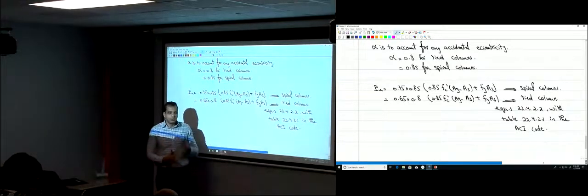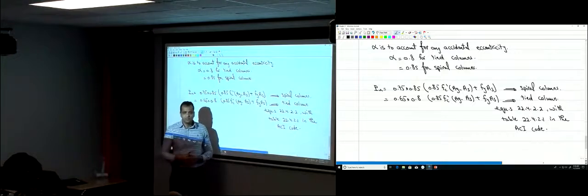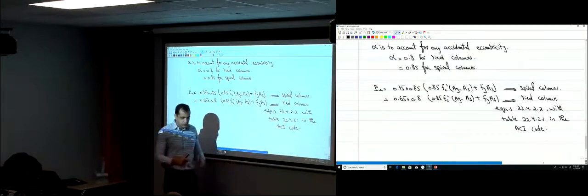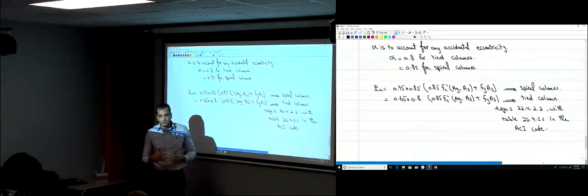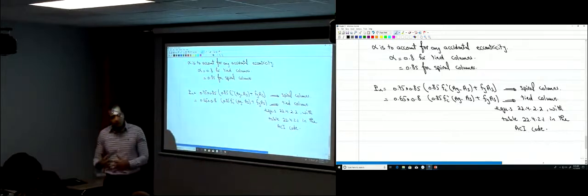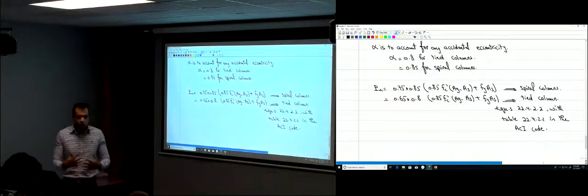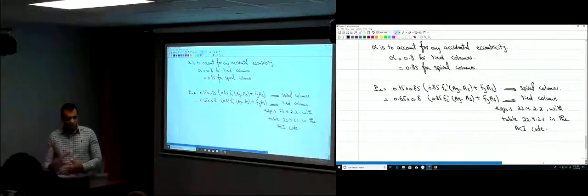So you either select a rho and find the area gross, or you can assume dimensions and find how much steel would fit with those dimensions. You cannot design for both. You just have to assume one of them, or start with knowing one of them and then find the other one.